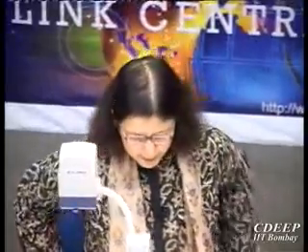So this is the amount of jitter which will come inside. It means that if you have a jitter, because jitter will appear as phase noise, therefore, if you have phase noise within an offset of 5 megahertz from 500 megahertz, this will come into the loop. The remaining part will get attenuated. Do you know about phase noise? Okay, briefly I will explain what happens.